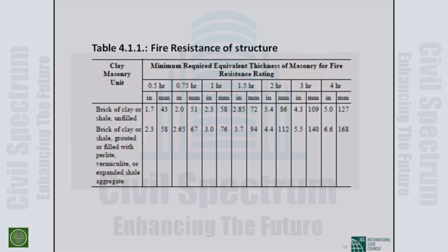In Bangladesh, more than 99% we use solid brick. Now we are gradually moving to hollow brick or unfilled product, but at this moment we are mostly with the solid brick. Unfortunately, solid brick data is absent from this BNBC. So for that you have to go to ASCE 29 again.